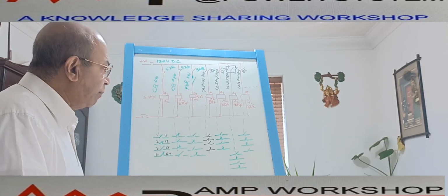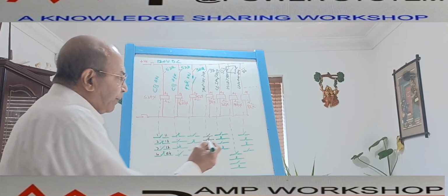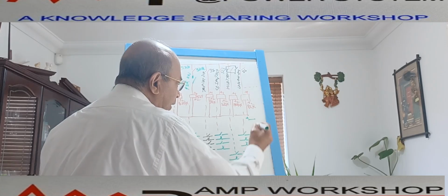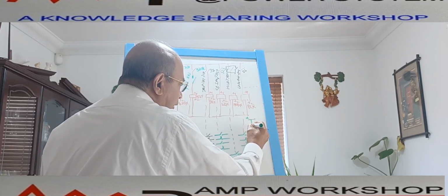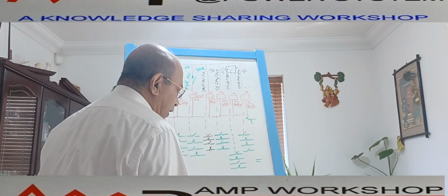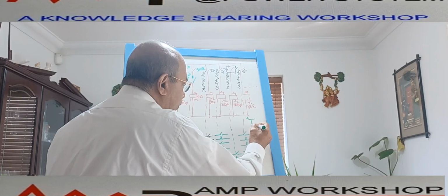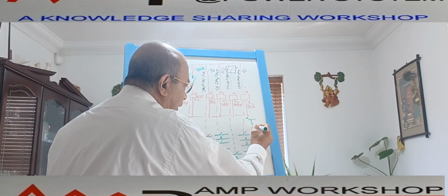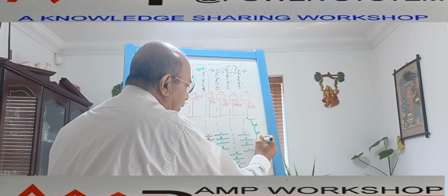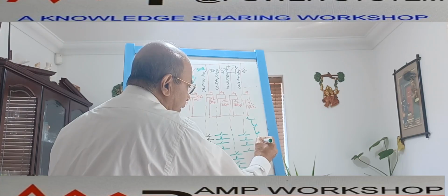If we want to draw that, suppose this is a positive supply and this is a negative supply. And there is a breaker auxiliary contact. You can draw the breaker auxiliary contact in the USA standard, but okay, now this is the European one. This is a breaker auxiliary NC contact. Then there is a spring charge contact, and then there is a DC motor here.